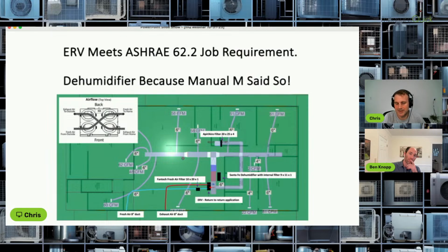And so it's just a little bit of taking the time to say, where can the equipment be mounted? How can I optimize my filtration strategy? All 3 of those filters are MERV 13, super awesome. And another benefit, when you can oversize a nice high quality MERV 13 filter, is that it gains you so much benefit.